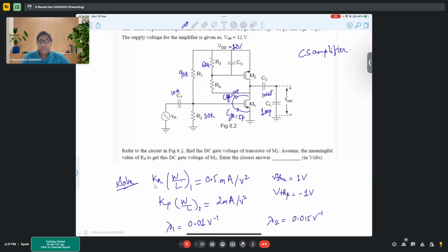In the linear region, particularly if we go to such small nodes, let's say 12 to 15 nanometer, because the length is small, the resistance would be small, right? But the resistance would majorly come from your depletion region. The drain side depletion region will give you a lot of resistance. And if you still want even higher resistances, then you can use the gate side, because we say that there is no gate leakage and everything, but there is still gate leakage.